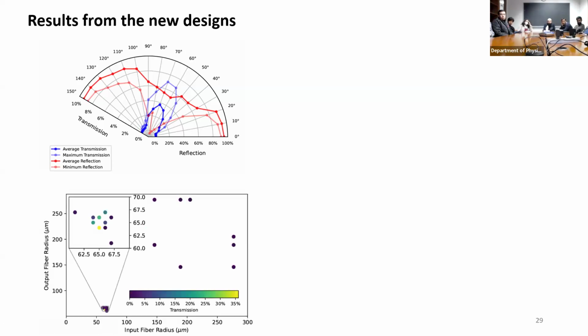And then I did a bit of a statistical analysis with different fiber mirrors to see whether the ablation profile or the size of the radii of curvature makes a difference. And actually with up to 60 micrometers, if we use fibers, you can go up to 35% transmission. So transmission went from 1% to up to 35%. So if you want to make a filter out of it, or if you want to have percent enhancement, you can actually get high transmission, I would say, still higher than before.